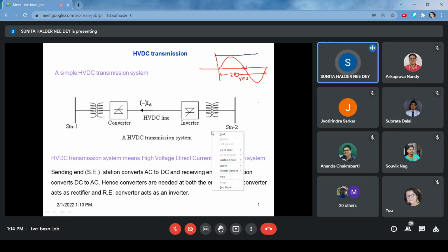When there is saturation of the core, if you see the phi-I curve, with I on this side and phi on this side, then the phi-I curve is like this. If we draw the normal magnetization curve, and if you have forgotten, see your first year notes, beyond the knee point the slope is more or less parallel to the x-axis.